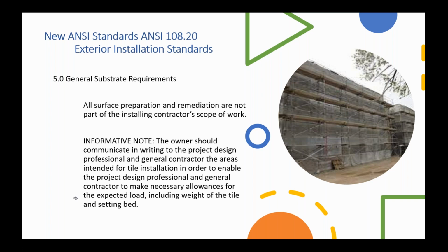It could be thinner, but because of the shape of it and so on, it says it's equal to a 20 gauge stud. The important part there is that it requires blocking and things like that in order for it to support a good tile installation. And so this puts the burden of the substrate on the contractor, not the installer.